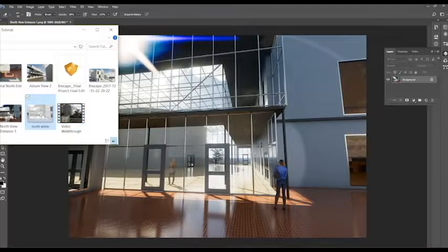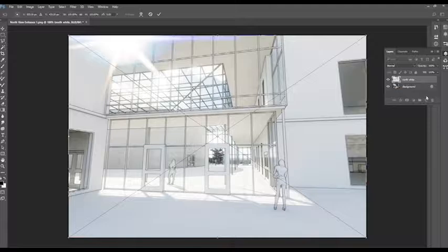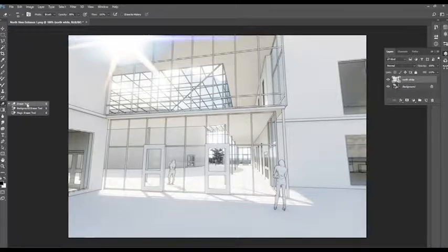I just plop the same view on top, so the layer on top in Photoshop is a white one, and the one below it is the rendered view. And I just open up an eraser tool in Photoshop, very light setting on it, and am just revealing colors from behind there, and also the shininess on the texture.